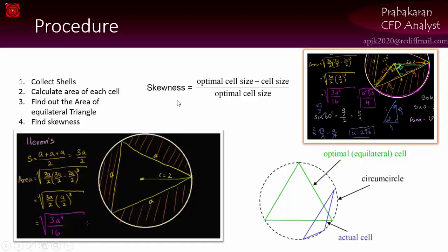Whatever I explained is for Fluent. This is the explanation you need to understand about skewness. So for each element, ANSA calculates these things and reports them to us. Today we are going to manually create a script which does the same thing that ANSA's element information does.